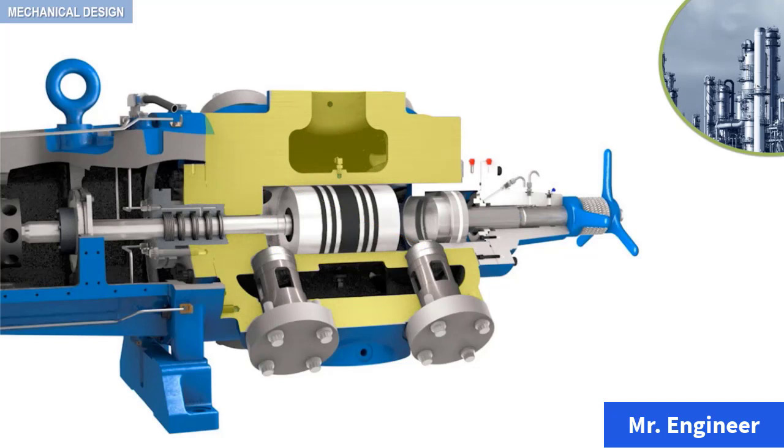A typical reciprocating compressor cylinder consists of a barrel, usually water-jacketed, with a front and rear head. In some designs, the rear head is an integral part of the cylinder barrel. This is the case here in our example. In others, it is a separate bolted piece. These heads are also water-cooled to remove the heat of compression. Provision is made in the rear head for the pressure packing as highlighted here.